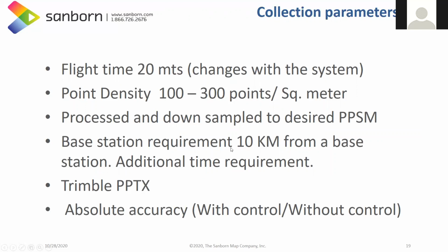And this base station requirement is primarily based on our experience. It is 10 kilometers from a base station. But nowadays with Trimble PP-RTX, in the majority of cases, you can get away from the base station requirement. So that's one of the advantages, you can collect the data without the base station.